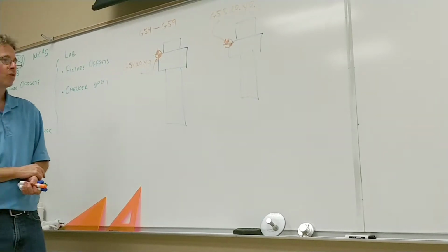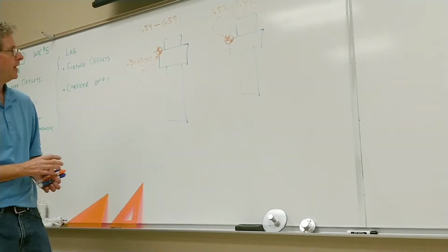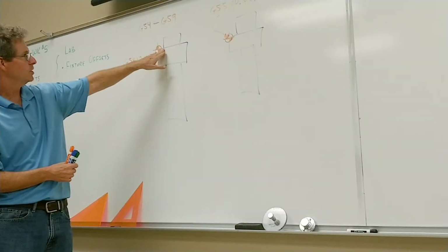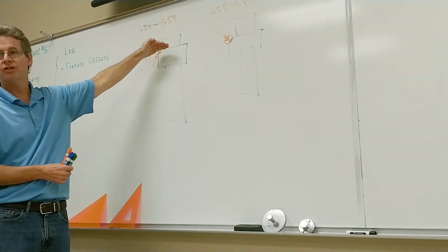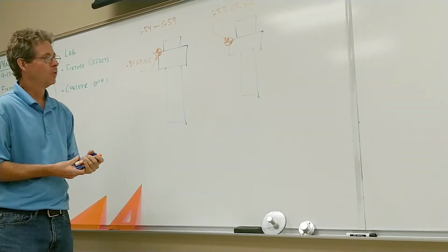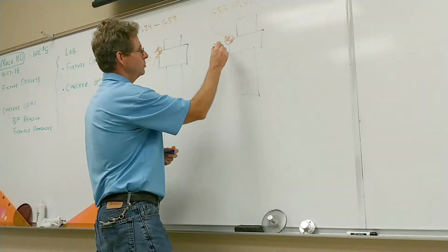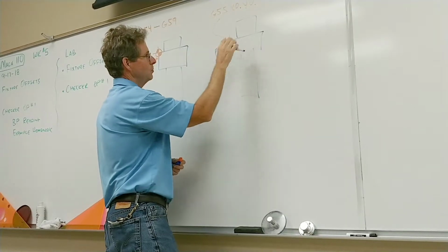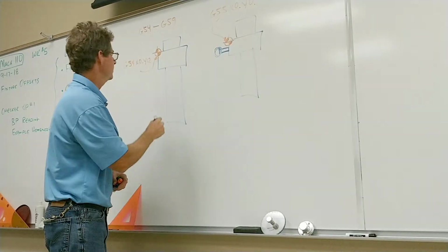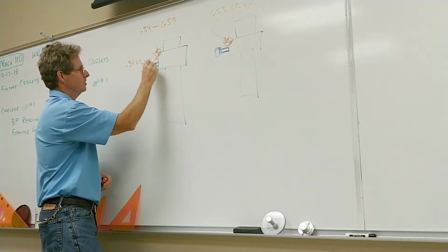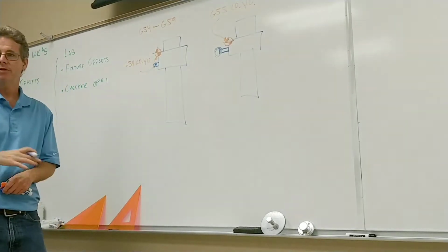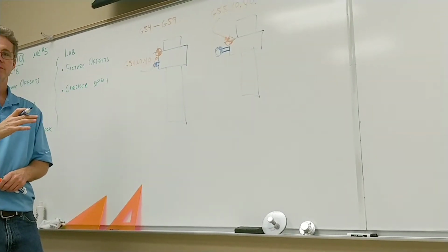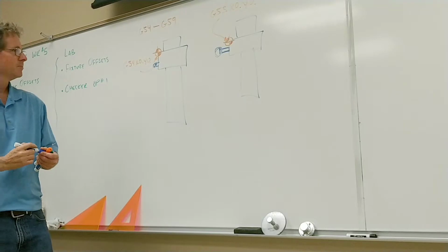Okay, so the way you can help prevent that is to always set fixture offsets against positions that are never going to move. If you were going to put a vise stop on the table, you'd want a vise stop typically on this side too. That will control the part from shifting this way, and then the same thing here. Put a vise stop on that side. That will bump it up against that every time. You get a little more reliable product.